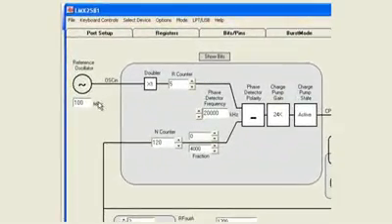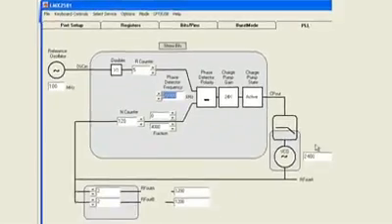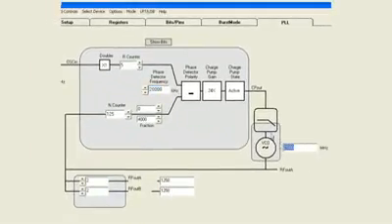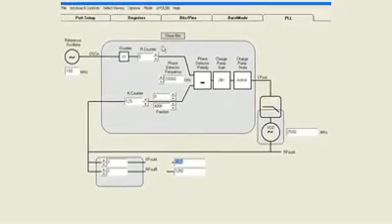On the CodeLoader software, we start with our 100 megahertz input frequency, divided by 5, get to my 20 megahertz phase detector frequency, and then I program my output frequency. The charge pump gain I can program by right mouse clicking to make it go down or left mouse clicking to go up. I can change the fractional denominator and the numerator as I please. If the output frequency is going through the divider, this is the divided frequency here.